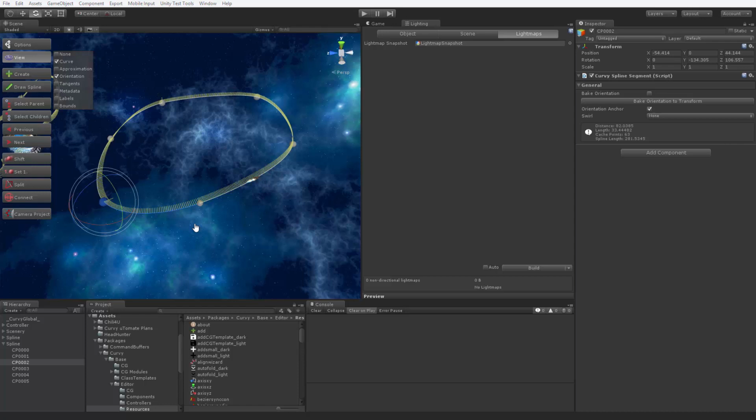Another useful option is furling. Let's say we want our ship to do a barrel roll from control point 4 to the end of the spline. We can, of course, achieve that by chaining half a dozen control points marked as orientation anchors. But that will take time and won't always be convenient, due to dynamic mode attempting to link orientations using the shortest rotations. So, instead of that, let's try the option specifically developed for such a case.